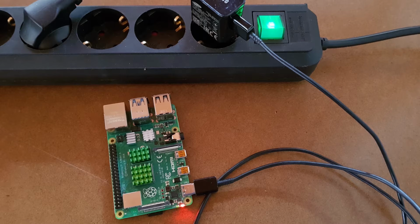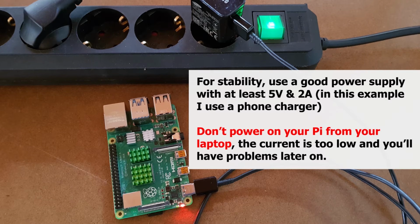To power on the Raspberry Pi, make sure that you use a good power supply with at least 5 volts and 2 amps. You can use an official Raspberry Pi adapter or even a recent phone charger. One thing to make sure is don't power your Raspberry Pi from the laptop directly. The current may be too low and you will have some problems later on.